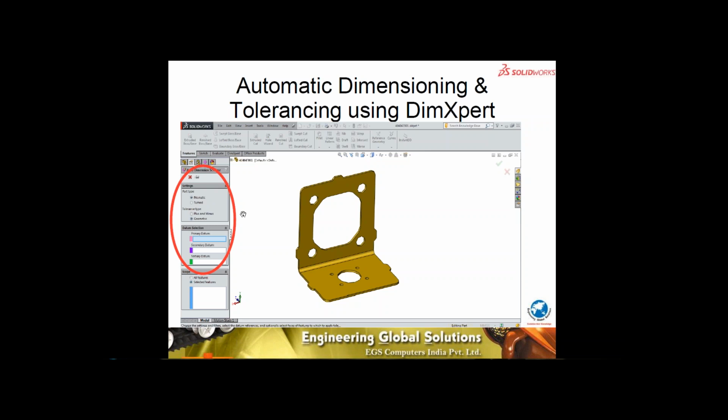Needless to say, design for assembly reflects itself in the choice of the datums that we put on the drawings: the primary being the first surface that touches in that part, the secondary being the second surface or the combination of surfaces that could touch the part when the part gets into the assembly, and the tertiary one. These three are required for orienting and positioning the part with respect to other components in the assembly.